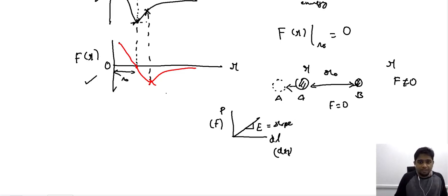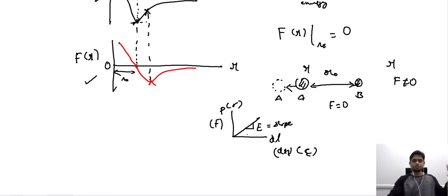In the same way, in the stress strain curve, the slope of the curve is nothing but the Young's modulus. So the trend of the curve remains the same irrespective of whether it is represented by load and elongation or by stress and strain.